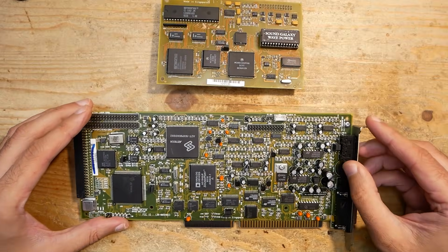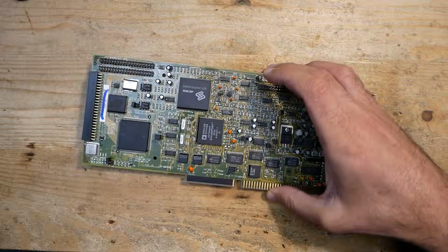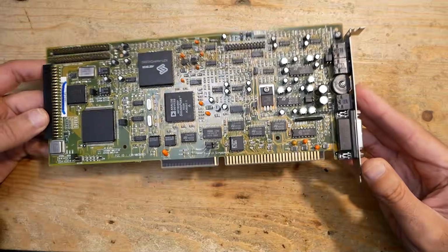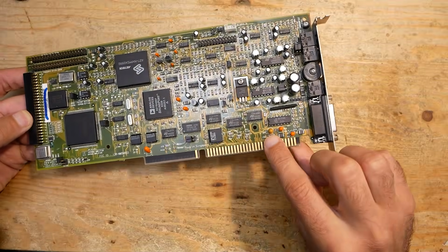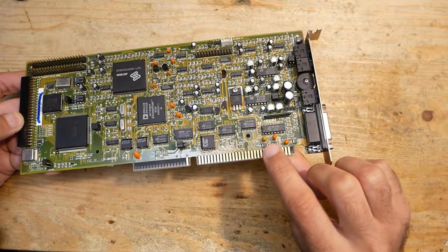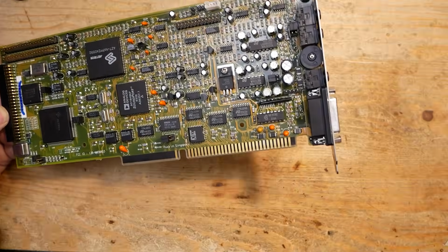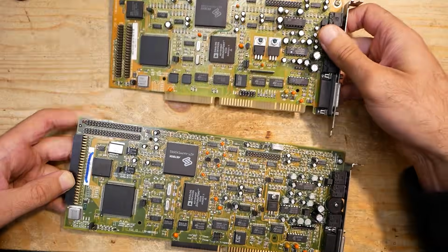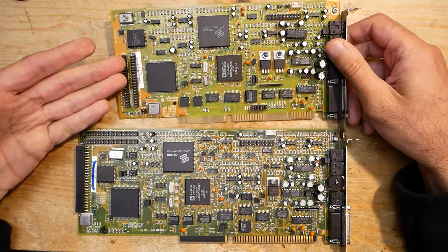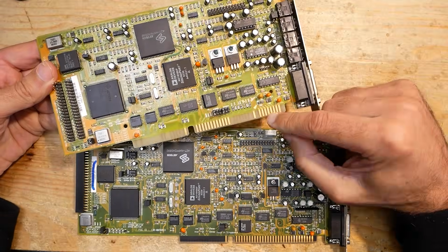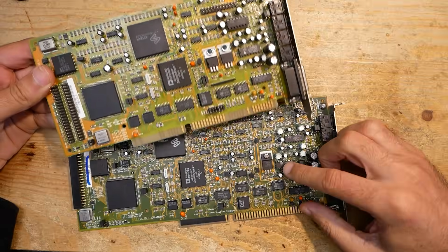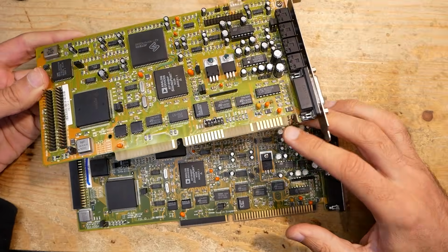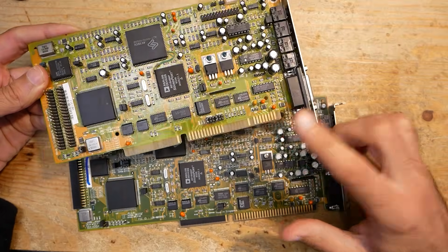I will do more experiments later, but if you tried it in the past, please share your experience in the comments. And in case you already forgot, this is the third card on my to-do list today. Off camera I already replaced the ferrite bead on the capacitor and I tested the card and it's fully working. I decided to skip the details because it is absolutely identical issue as the one which was on this basic 16 card and which I fixed in the last video. If you are interested and didn't see that one, feel free to take a look.